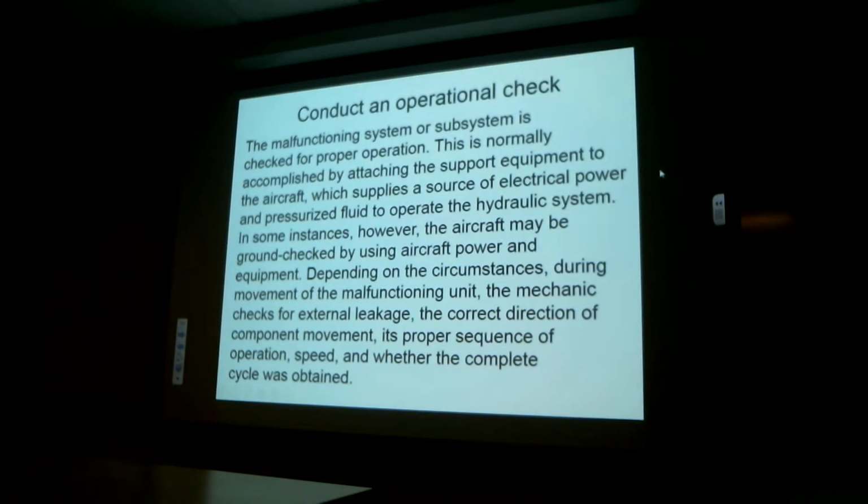Remember also, they pointed out in that video that it's sometimes possible to overlook a problem as a result of not using aircraft supplied power. If you're using a ground power unit to substitute for maybe an aircraft pump or an electrical source of power, you're bypassing a portion of the normal circuit or the controlling circuit for what you're inspecting. So you may overlook a problem as a result of not using aircraft power, either electric or hydraulic. So, okay, that's the operational check.